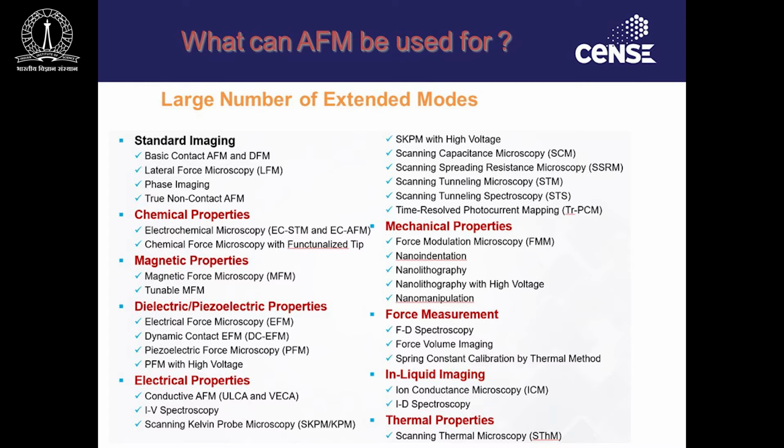So these are some standard imaging techniques which we spoke about: tapping mode, contact mode, non-contact mode. You can also do magnetic force microscopy, lateral force microscopy. Then there are other chemical properties measurement, then the electric piezo properties measurement, electrical properties measurement. You can do a lot of other things, but all these things will differ from machine to machine. Whether a particular machine is capable of doing it or not will depend on whether that company provides that particular module, and if that particular module is there, then whether you have bought it for your system. Depending on that, you can do all these